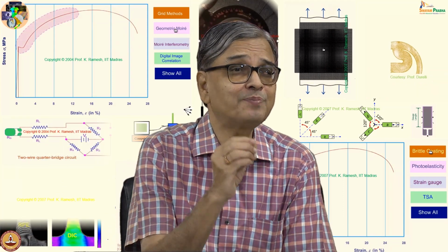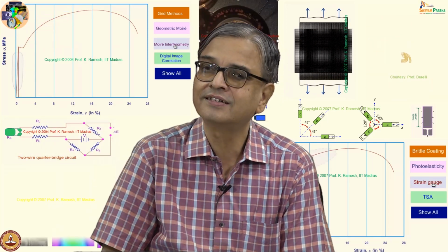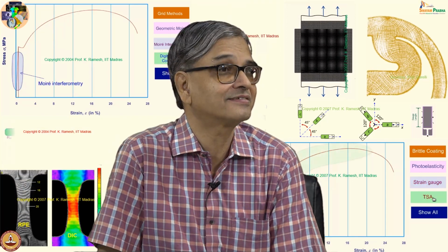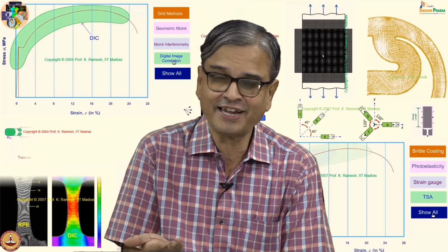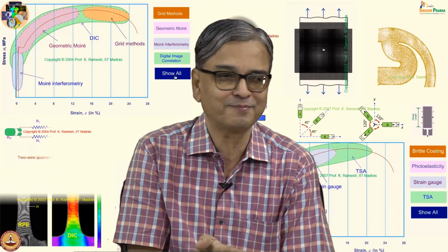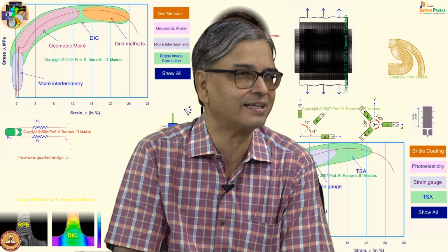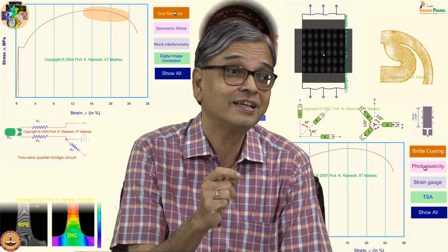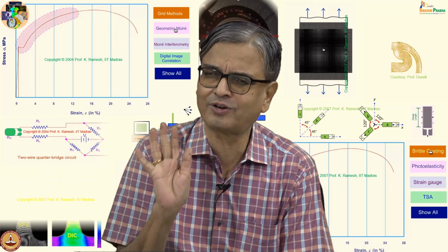Now, I have a very small tiny strain gauge. I am going to pass current through this. This also acts like a micro heater, I squared R loss is there. Because I am going to measure 10 power minus 6, you can't feel the heat. In a domestic heater, it is 1000 watts. This will be very small wattage, okay, 0.04, 0.06 or something like that. But that heat generation also affects your electrical response. So, you have to be very sensitive that you are measuring an extremely small quantity.